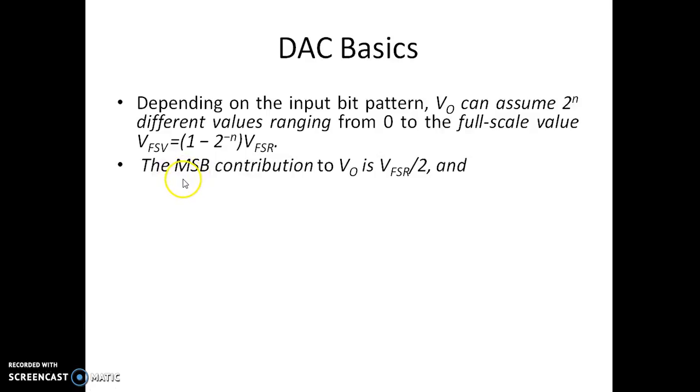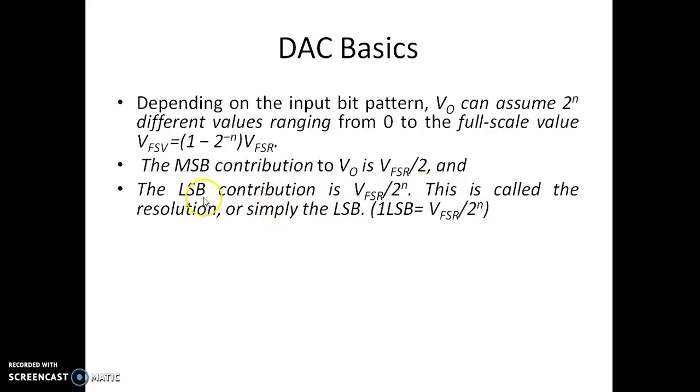Now the contribution of the MSB to the output is VFSR divided by 2. So the MSB will contribute half of the full scale range voltage, and the LSB contribution is VFSR divided by 2 power n. This is called the resolution, simply the LSB. So 1 LSB is equal to VFSR divided by 2 to the power of n.